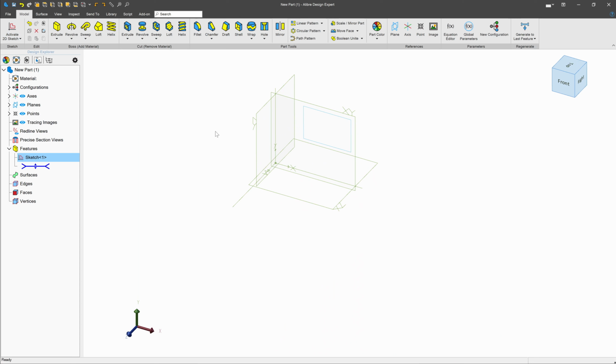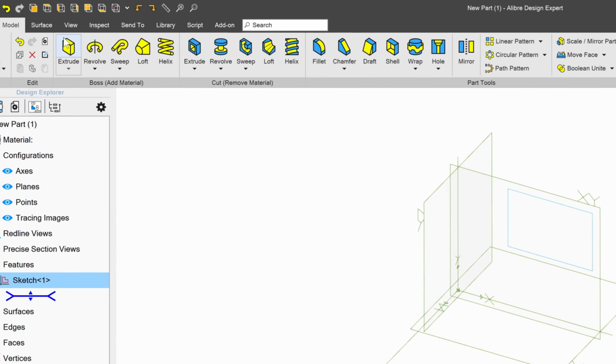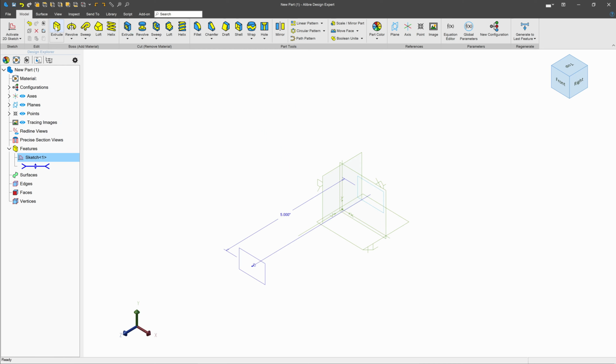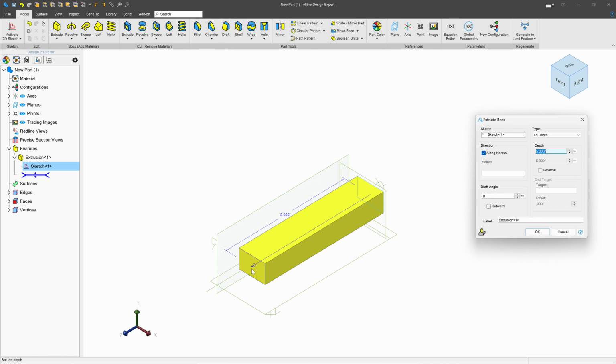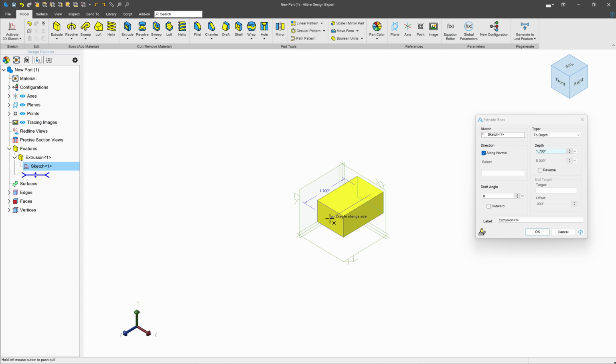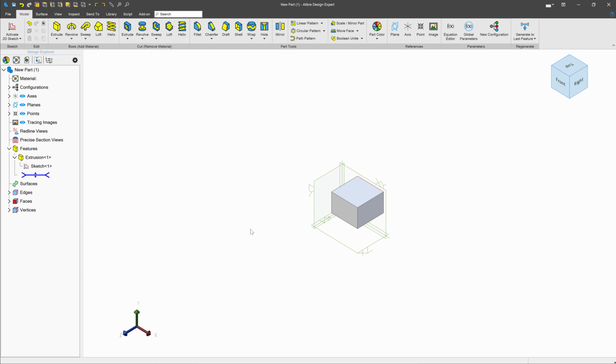And there are certain tools that we can use to turn this rectangle into a 3D model. I want to show you that now, just so that you know what you are doing and what your end goals are when you create these sketches as we go through sketches. I have this option to extrude here. And when I extrude, you can see that I am pulling that rectangle into a third dimension. And I can take this blue arrow here and I can drag it to change the length of my extrusion. So this is known as extruding because just like the manufacturing process, we're taking a profile and pushing a 3D shape out of it. So we can extrude and make this sort of rectangular prism.